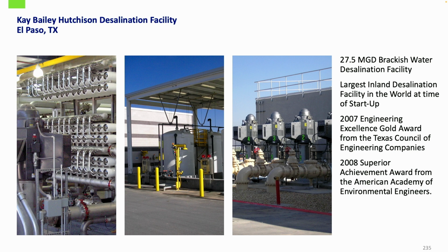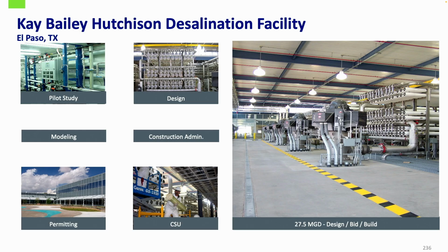It won several awards, and it involved all kinds of studies. There were pilot studies done that took over a year. We looked at recoveries, operating the plant up to 92% recovery, looked at using various anti-scalants. We looked at different types of designs, and you could see from our old plant, this is a very unique design, and this was done just to handle the airflow through the system, where I learned on other projects that you would get a lot of fouling of the membranes just due to the oxidation of iron and manganese. So this solved a lot of the problems there.